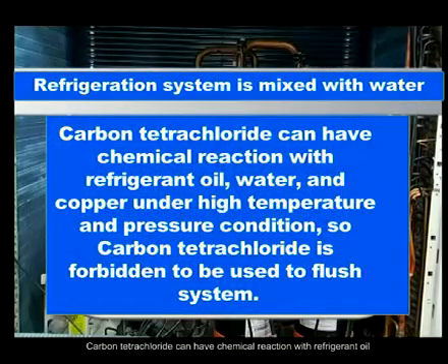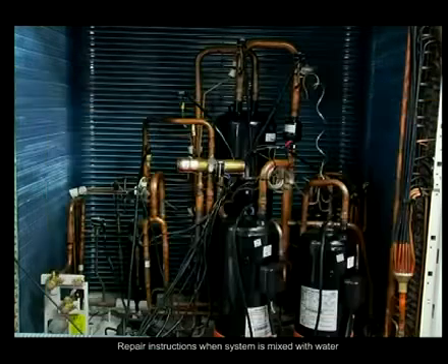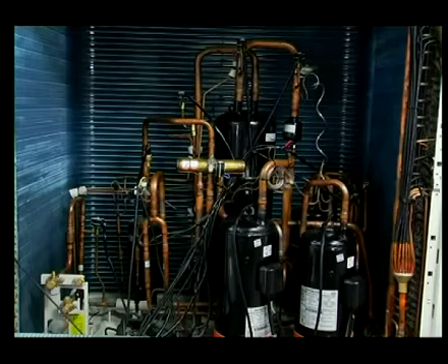Carbon tetrachloride can have a chemical reaction with refrigerant oil, water, and copper under high temperature and pressure conditions, so carbon tetrachloride is forbidden to be used to flush the system. Repair instructions when the system is mixed with water.